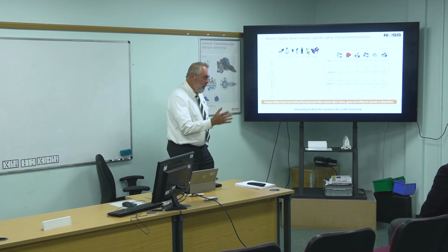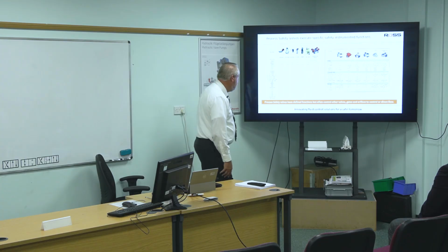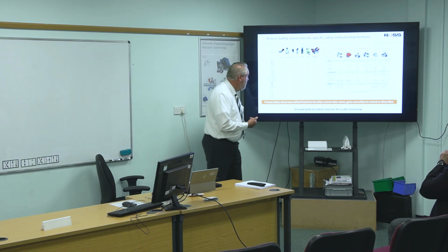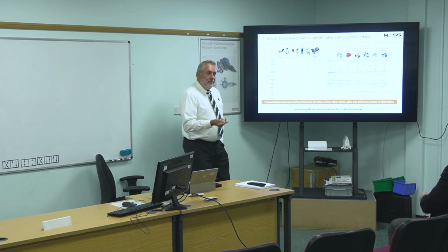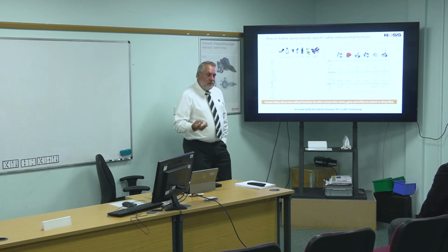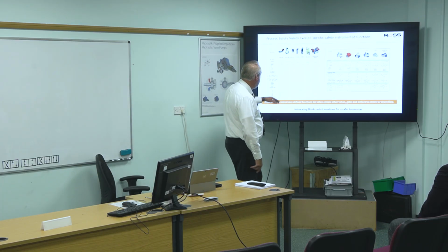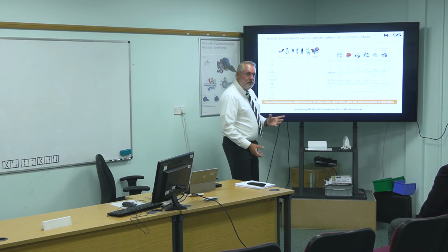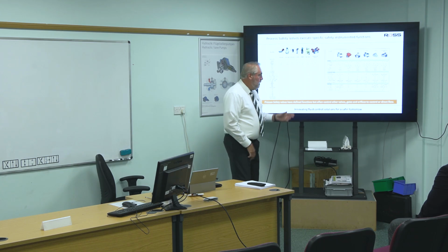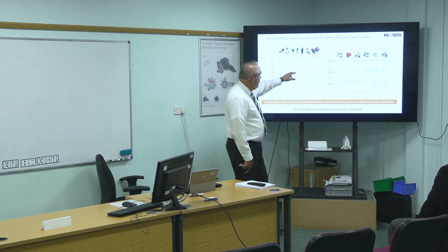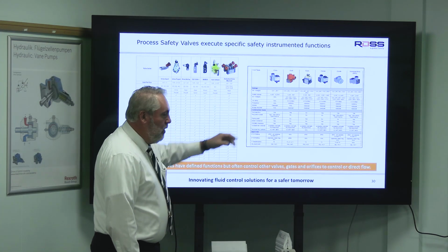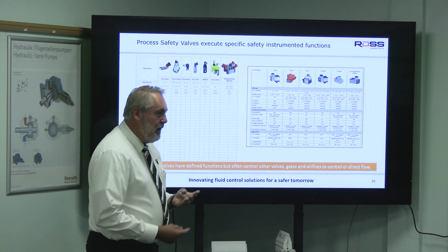And then the process world is different. You may have some of the same functions like doing a safe return or a safe exhaust or a safe load hold, but the products are rated differently. And if you look here, these will have ATEX ratings or class and div ratings. So these are explosion proof ratings. They also will have ratings like, for example, 1 out of 2, 2 out of 2.